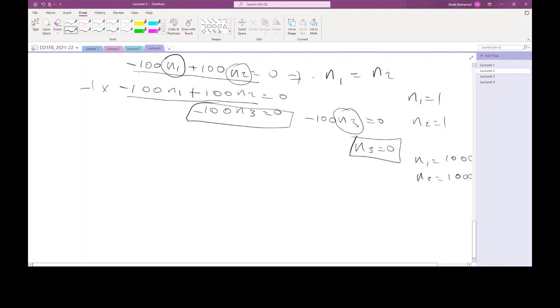I said you really want to normalize things, because you want to have the length of the normal direction to be equal to 1. Because as I said, you always try to find projections using the normal direction. If you have some length to the normal direction, you are going to magnify or probably scale down the forces you are looking for. So you always take the normal direction to be equal to 1. Okay, so in this case, I'm going to assume n1 and n2 are equal to 1. This is the easiest for me.